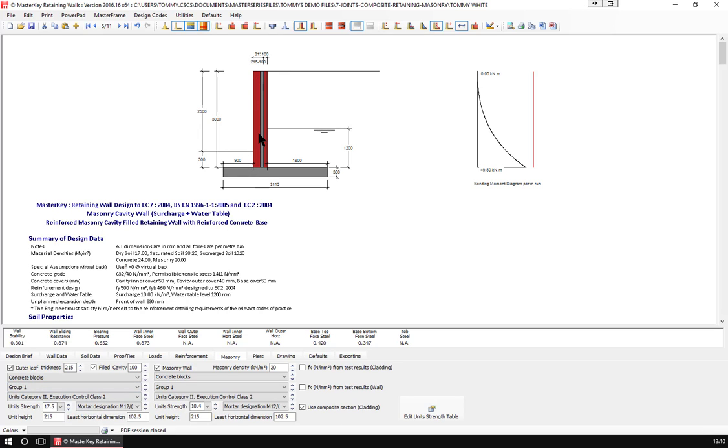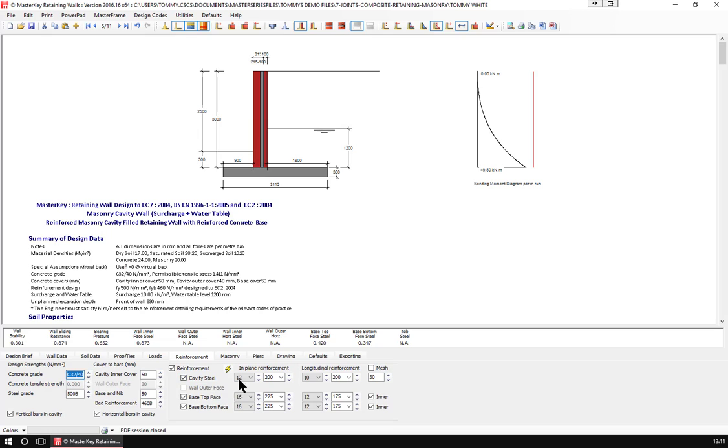And you will notice, for those who are not experienced, the wide block is on the outside, because again that is your compression zone. So your design, this is just formwork, your design is from the center of the cavity for the rebar to this compression zone, and we will see that this works with cavity reinforcement 12s at 200.